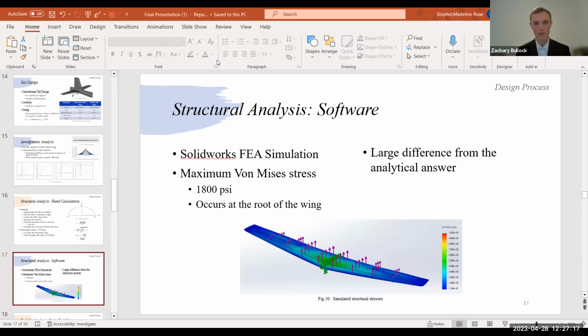We constrained it with a lower expected yield stress than the hand calculations were run with, but there was no other specific constraint taken for anisotropic materials. Okay, yeah, so I doubt how accurate this FEA actually is then. For one, SolidWorks is limited on their mesh size. It assumes fully isotropic properties. It doesn't account for print layers at all. I would be very skeptical of this FEA.